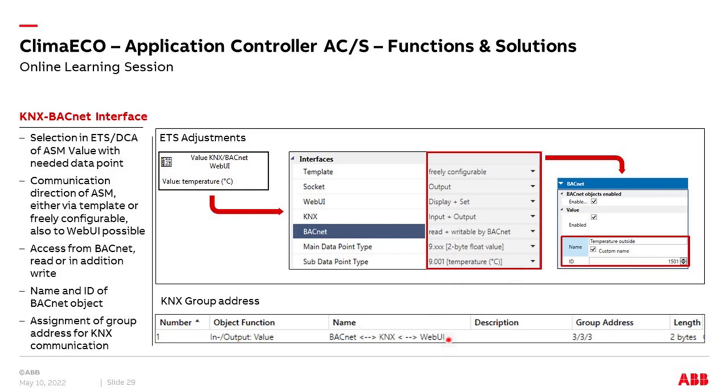Of course, finally, to this group object created here out of this, you have to add the group address linked to the real KNX device behind. Any sensor, whatever you have, any actuator. This is, of course, additionally necessary. But then, more or less, you have created your pure KNX to BACnet data point. And this you can do 500 times if you want.